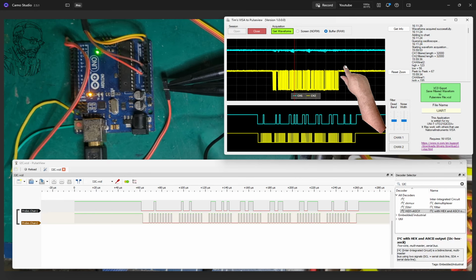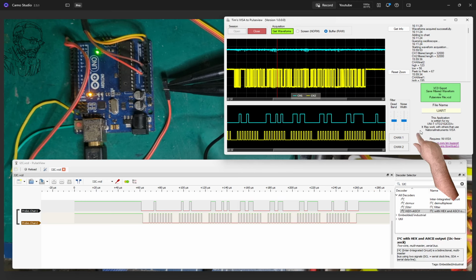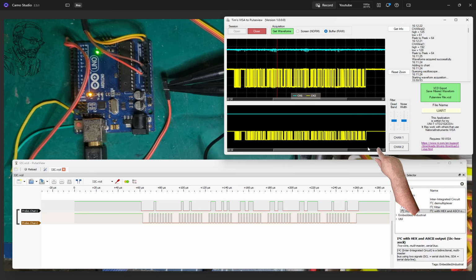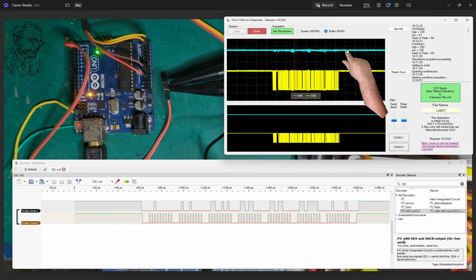So what this program does, we can have a look and we can see the data there. Oh no, sorry, I haven't filtered it yet. Yeah, so we're looking at the right thing. So that's our filter there, and you can see this is a nice dead line. That is held high at the moment because there's nothing happening on the RX. We're not sending any serial in, we're only sending serial out. So this is basically a flat line, and the way things work is it's normally held high and pulled low to give you a message.